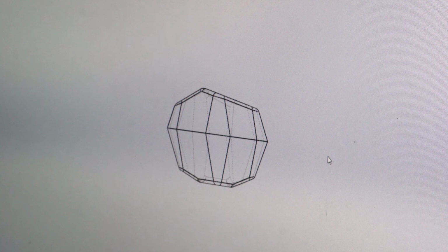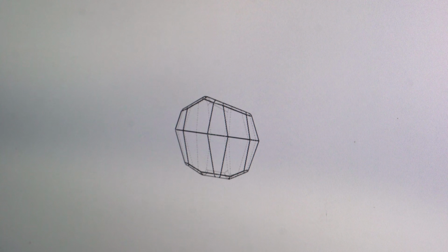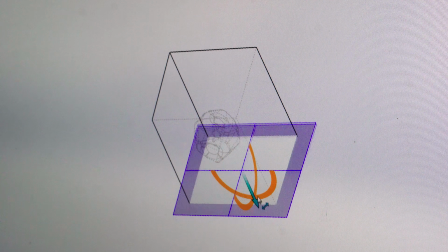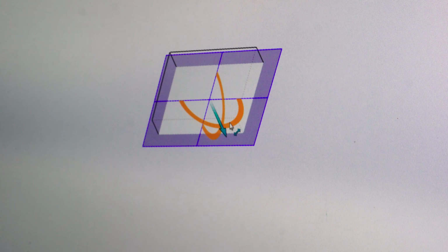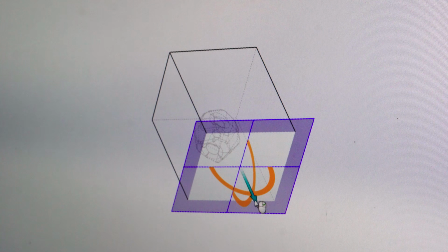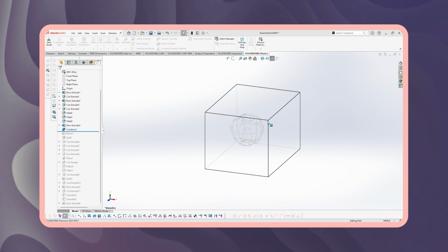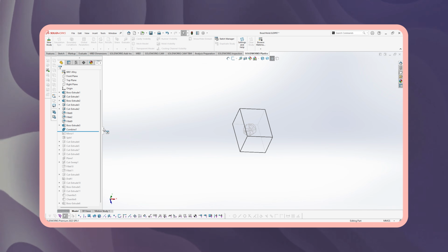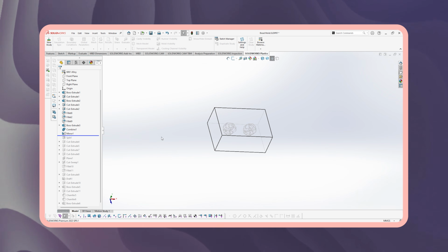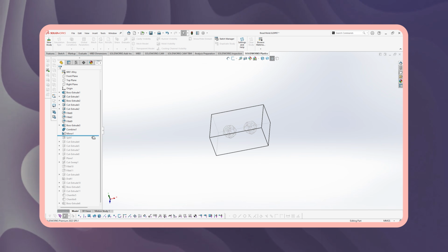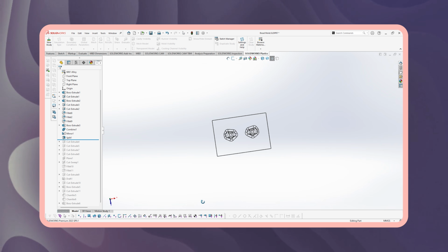Once the part was finalized, the next step was designing the mold. And this is where injection molding becomes very different from 3D printing. You cannot just design the part, you design different features on the mold. This mold is a simple two-part mold with two cavities. To create the cavity, I used a Boolean operation, basically creating a block around the part and subtracting the part from it to form the mold cavity.